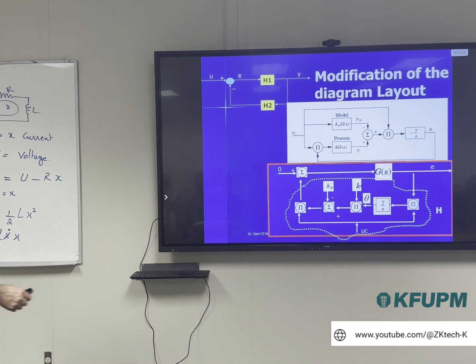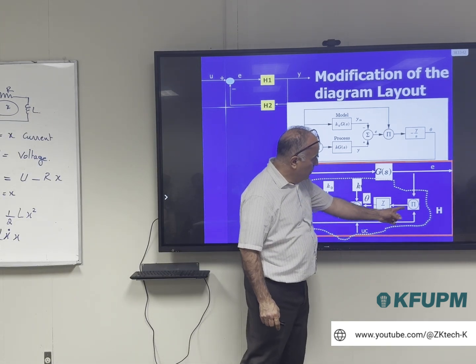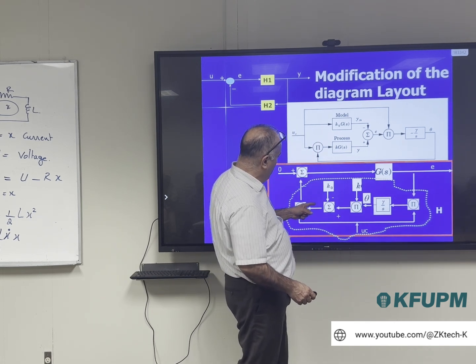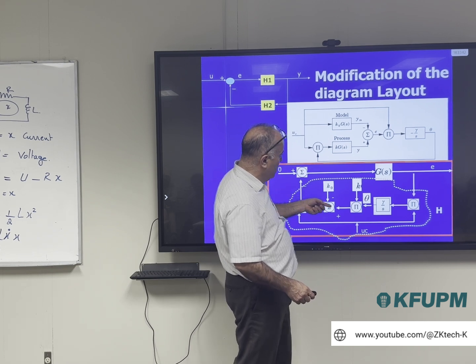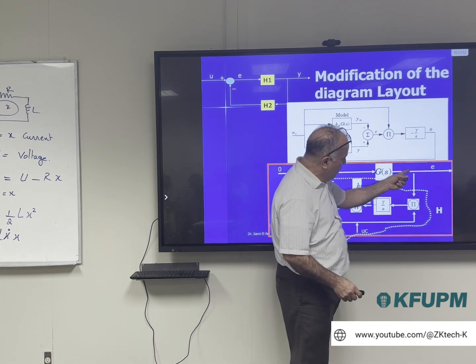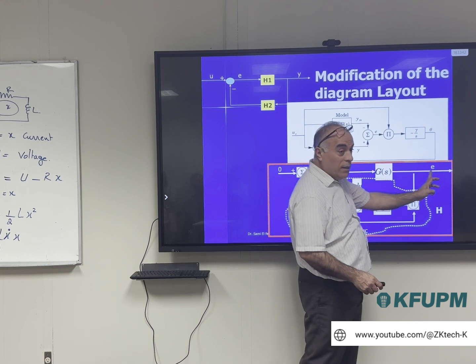So we have all this block. This is UC. If you look at this, you have theta multiplied, this is the feed forward, so theta multiplied by K0, which is the gain for G(s). That goes through G(s) here, generates ym, y minus ym, so the error. So my output here is the error.